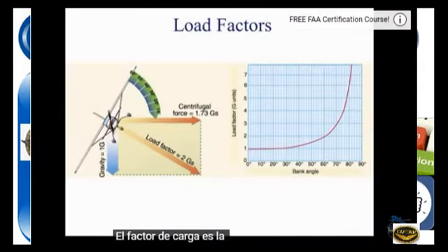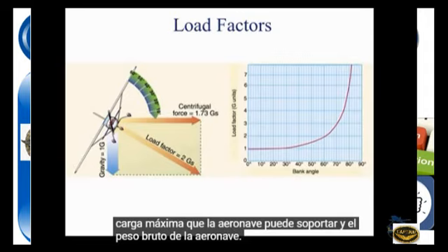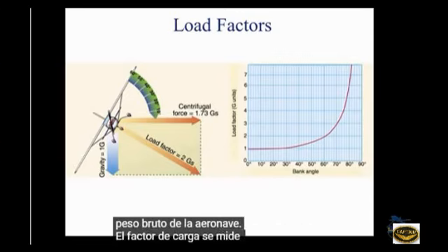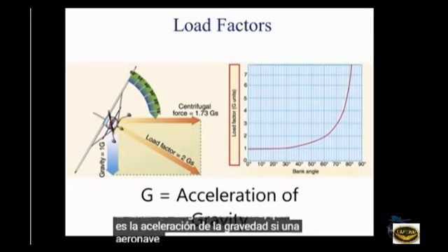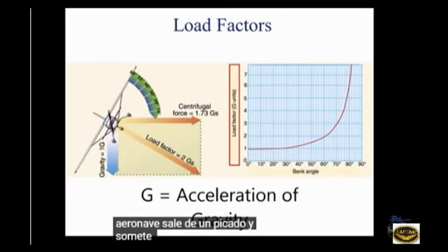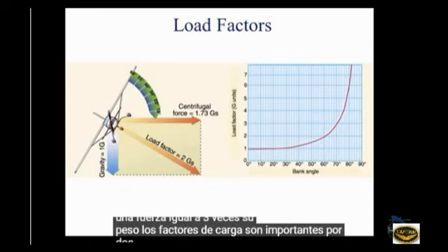Load factor is the ratio of the maximum load an aircraft can sustain to the gross weight of the aircraft. The load factor is measured in G's, which is the acceleration of gravity. If an aircraft is pulled up from a dive, subjecting the pilot to 3 G's, he or she would be pressed down into the seat with a force equal to 3 times his or her weight. Load factors are important for 2 reasons.